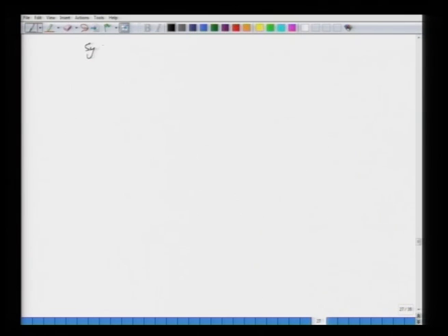This Sy is about 27% for coarse sand, and it is about 3% for clay type of strata, or an aquifer which consists of mainly clay, and this is about 44% for peat. So, you see that it depends on the kind of aquifer, the soil properties.